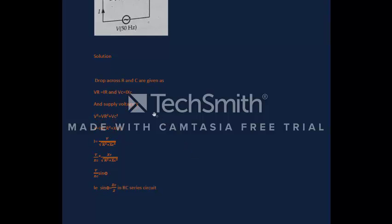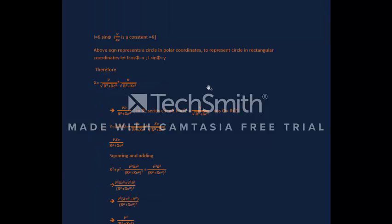And the supply voltage be V. So V square is equal to VR square plus VC square. V is equal to I into the whole root of R square plus XC square. I comes out to be V upon the whole root of R square plus XC square, which is V upon XC into XC upon the whole root of R square plus XC square. So it turns out to be V upon XC sine theta, where sine theta is equal to XC upon Z in a series RC circuit. So I is equal to k sine theta, where V upon XC is taken to be a constant k, as it's not a variable property.